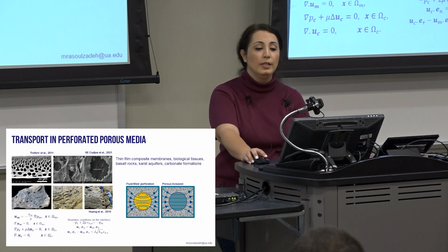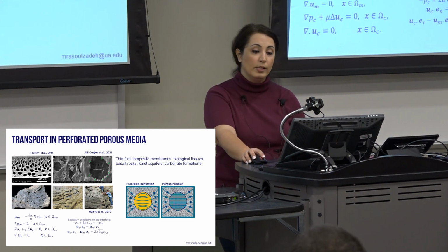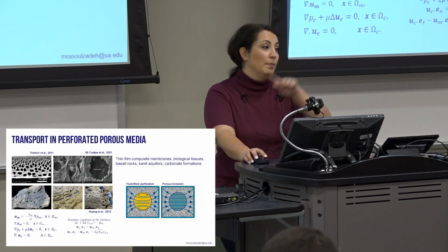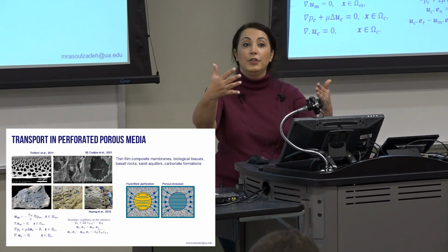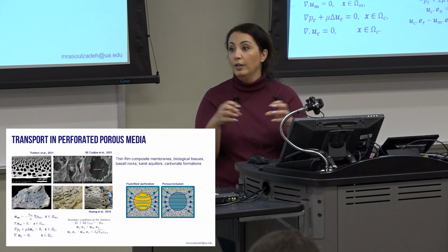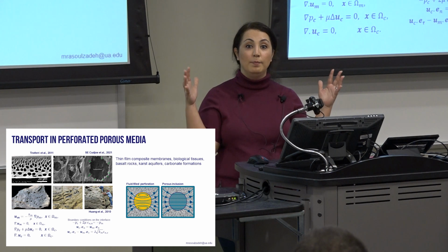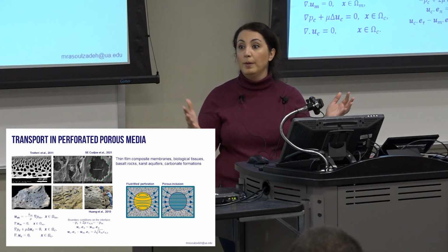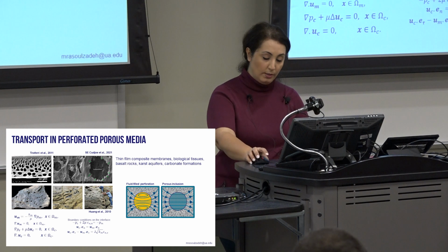Here, I tried to show you how the streamlines are structured when you have a free flow region and when you have a porous inclusion, to just bring your attention that when you have a free flow region, you may have some vortices show up in the perforations, and that actually reduces the effective volume of perforation from your medium. So we expect, I have these big holes, and the effective permeability should be high because I have open free flow regions, but those vortices actually reduce the effective volume of the medium.